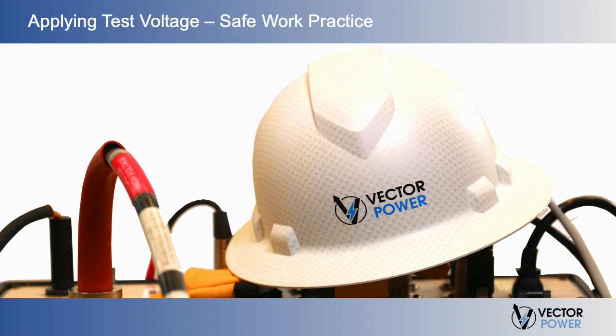Additionally, when testing insulation in many high voltage environments, it is not uncommon to climb ladders to reach connections on equipment such as transformers, with associated risk of working at height. In such situations, an otherwise harmless electrical impulse may cause the user to react automatically, with a potentially serious injury from a fall. Fully insulated clips on the test leads and proper PPE help minimize this risk.